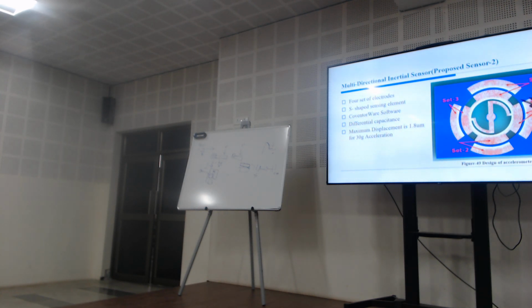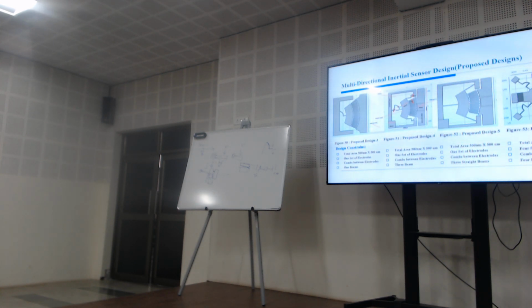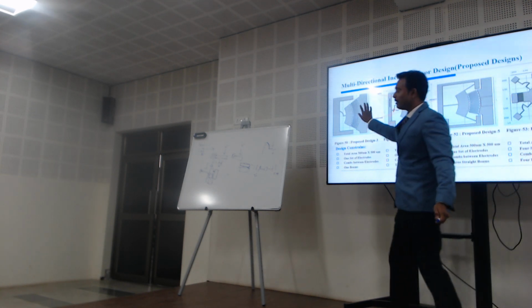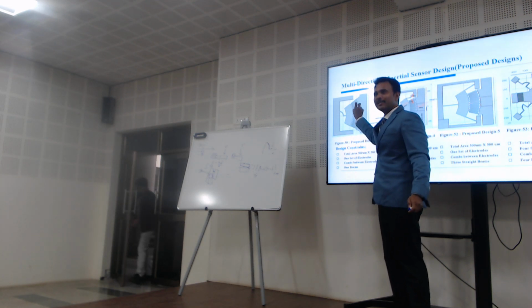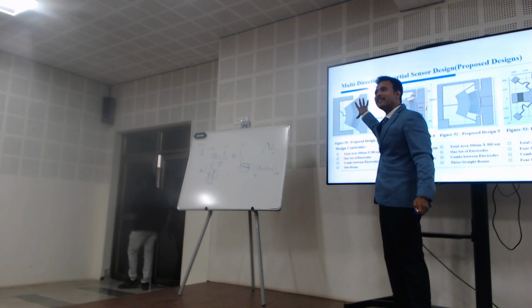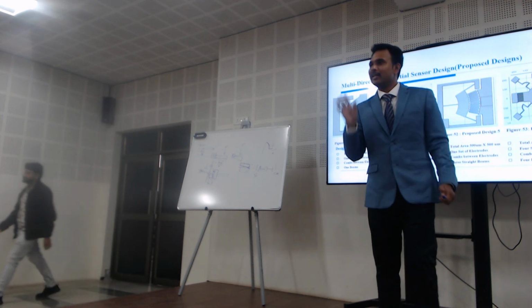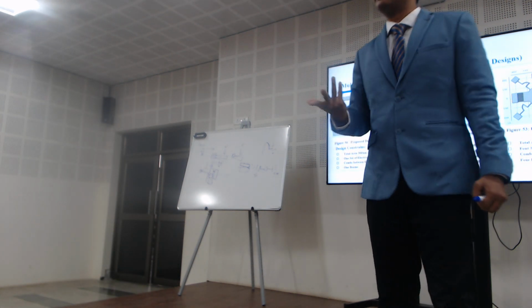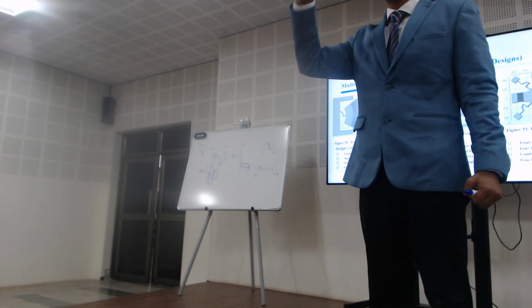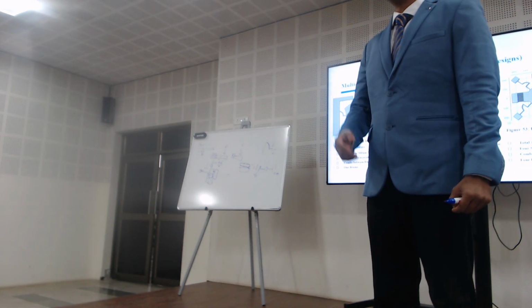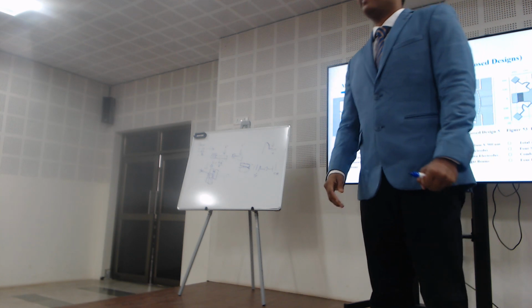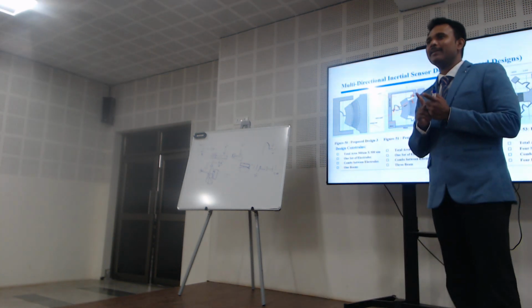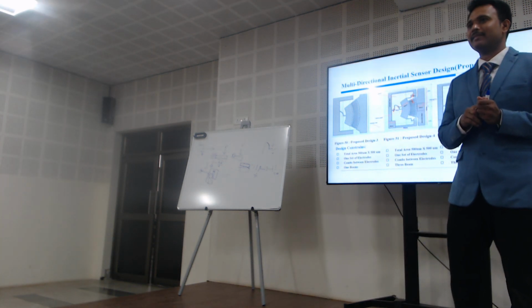See, you take only these two parallel plates, come with this same kind of parallel plates. Now is this area covered or not? Previously I left this area, now this area is also covered with our silicon. Now does my capacitance value increase again or not? So that is the effective use of the material and effective use of the area. We have to remember that while designing the sensor.